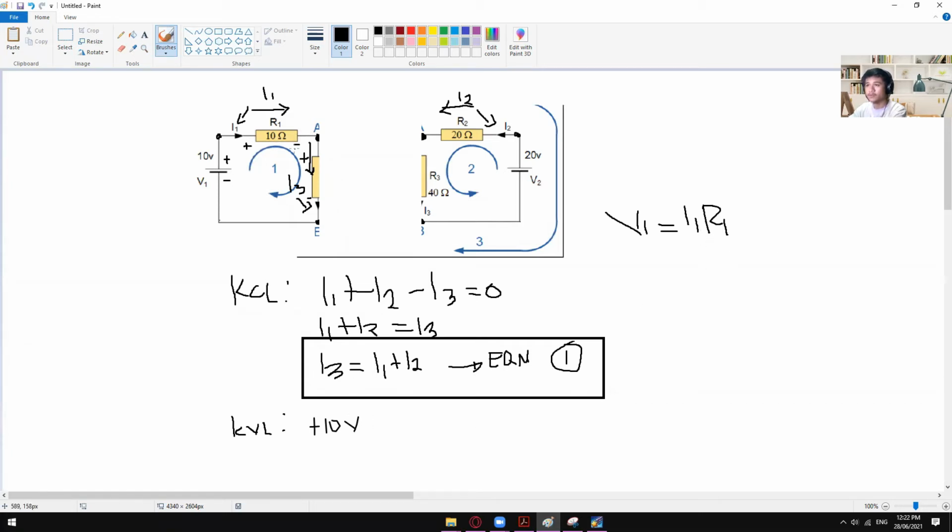Since we know that we're going to have a voltage drop, it will not be added to our voltage source. Instead, it will be deducted from our voltage source. That is why we have to consider the outer part. If you're considering the outer part, then you have to stick with the outer part. If you consider the entering part, the negative, then you have to stick with the entering part. Either of those two, you will get the same answer, as long as you're consistent. I always use the outer sign to finalize my signage.